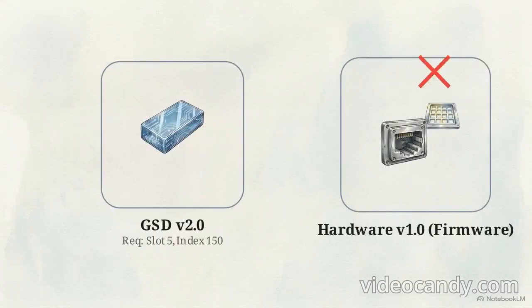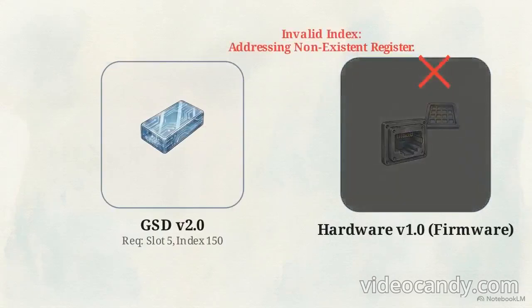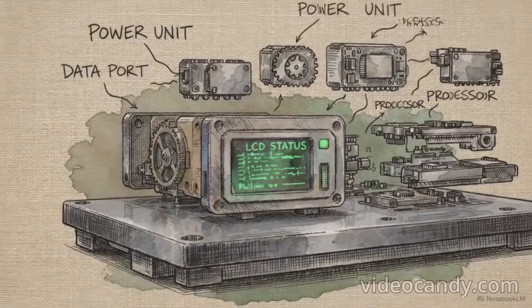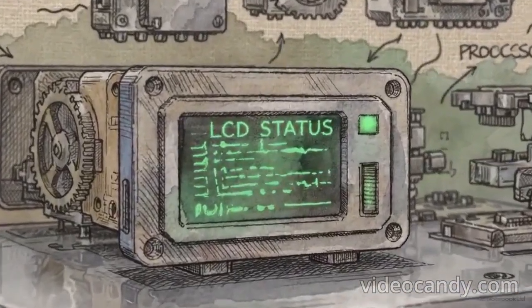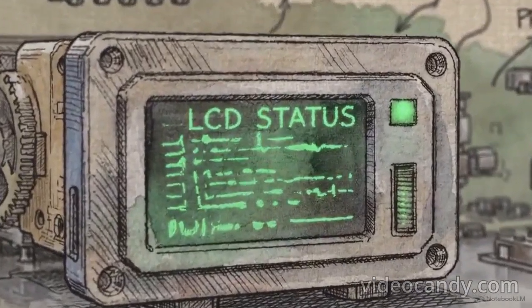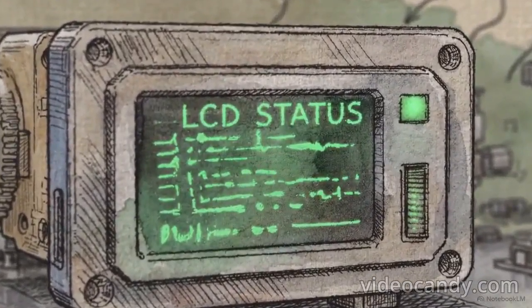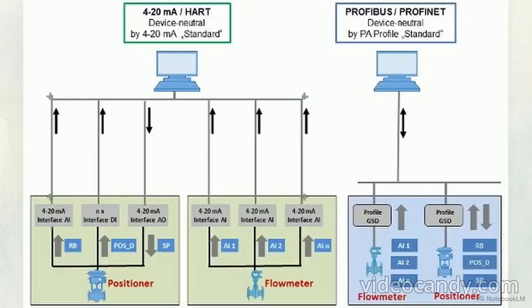Accessing these features requires strict version control. The internal logic declared in the GSD must exactly match the physical firmware installed on the slave device. If an engineer loads a GSD for version 2.0, but the hardware is running version 1.0, the acyclic burst will attempt to write to memory registers that do not physically exist, triggering an immediate bus halt. With correctly mapped parameter data, a simple I/O node functions as an intelligent, parameterizable station capable of local logic execution and advanced diagnostics.